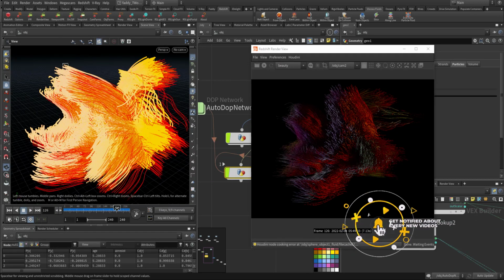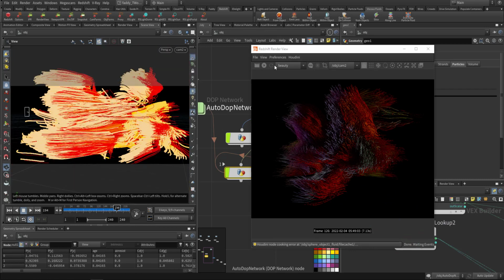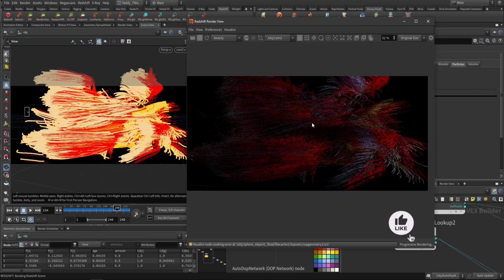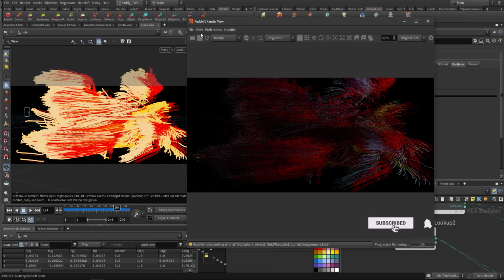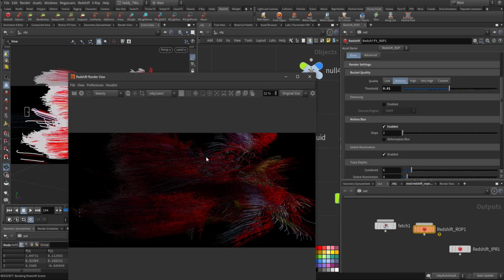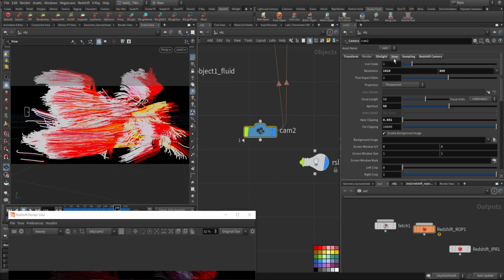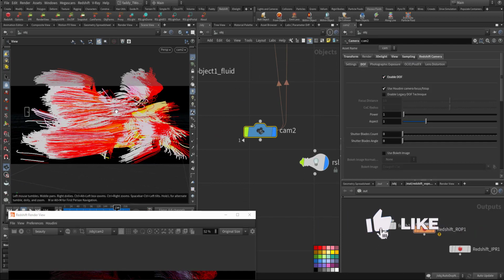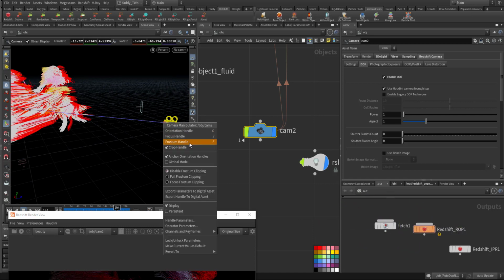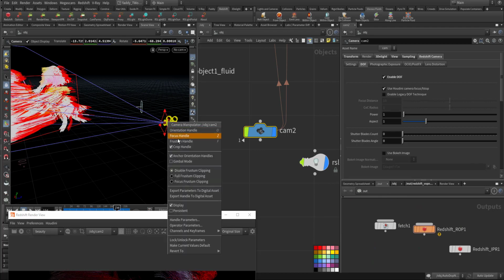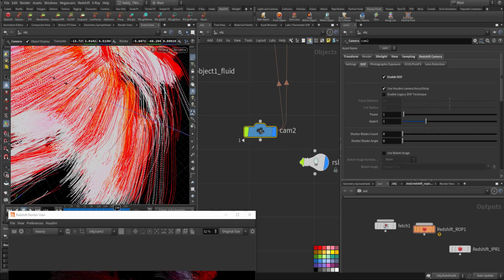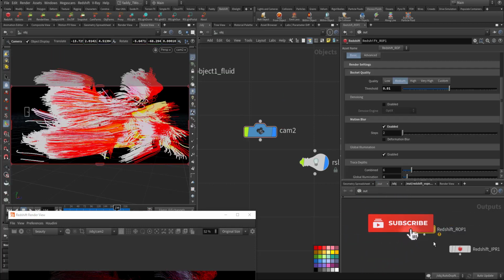Let me stop and go to another frame. Let's see the camera and render it now. Very cool. Maybe we can add also motion blur here, denoising motion blur. Let's add it, because what I did also, just to show you the camera, I activated the depth of field. If I choose the camera, let's move away, right click on the camera, and I have the frustum handle and the frustum, the focus. So this is focusing with shallow depth of field. Let's make it even smaller. Okay, let's point to the camera, and here it's activated.